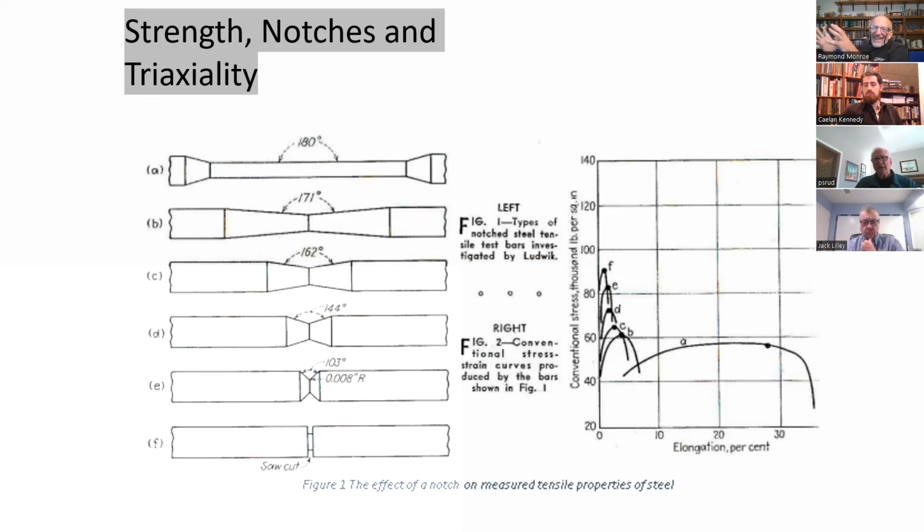So I was thinking today, when I was talking about it early on, that I bet the fact that we always taper it means that the ductilities we measure are uncharacteristically low of the material. That's why I asked the question. It's a great question. And it seemed to me that we were talking a few thousandths of an inch. Yep. Taper, right? It wasn't very much at all. In fact, if I remember correctly, the machine shops thought as long as you could measure a taper and had the smallest diameter in the middle, that's where it was going to break.